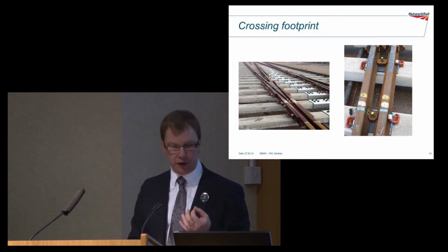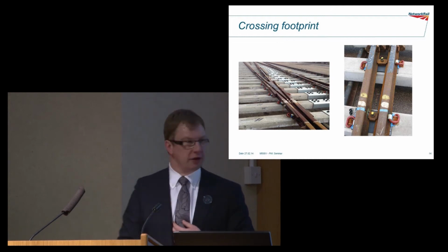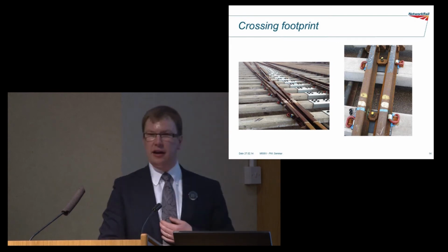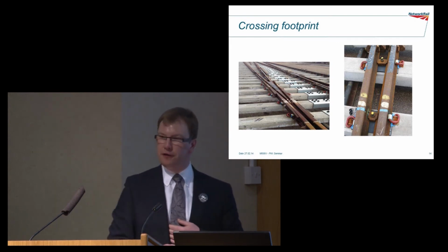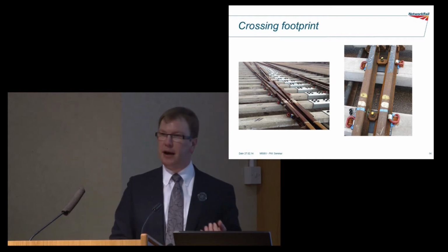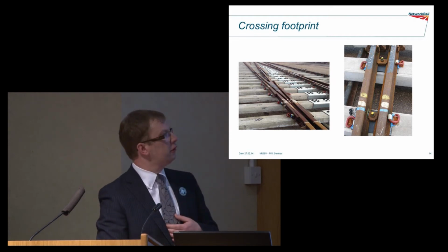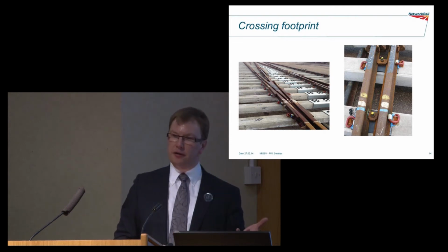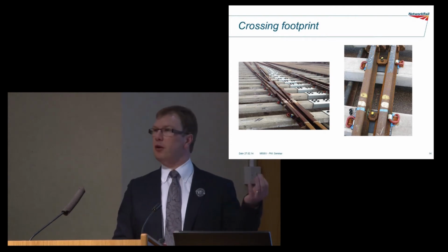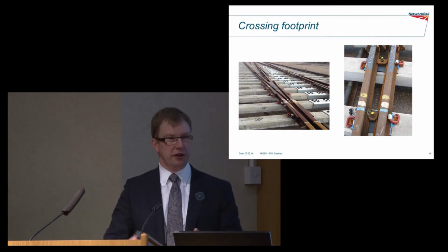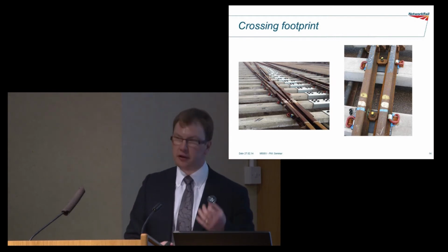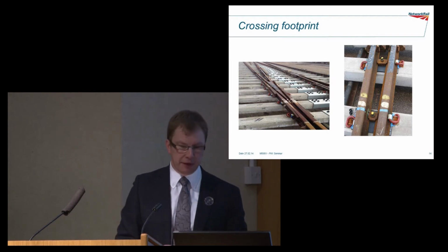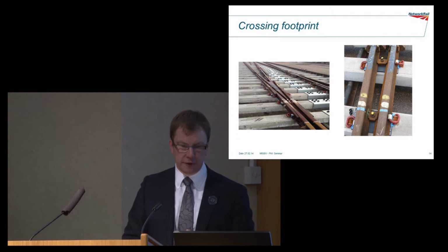of the crossing. Other things that have to be taken into account are the clipping arrangement, particularly in the middle of the V. There are different ways of doing this, and in the past some people have put blocks in, some people have used these clamps. If you end up with one crossing from one manufacturer with blocks and the other one that relies on clamps, again, you lose this interchangeability in maintenance. So it's important when we specify the footprint, we specify the holding down method and whether we're using blocks.